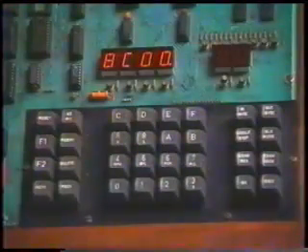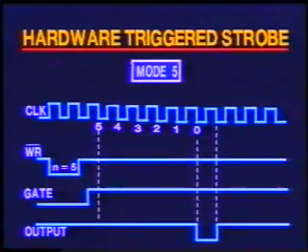The mode word and count value are loaded. The counting is started by the gate signal, that is, by hardware. A low-level pulse of 1 clock duration is generated when the count reaches the count value. The counter is re-triggerable. That is, when the counting is on, if gate is made low, the counting is made to start from the beginning.